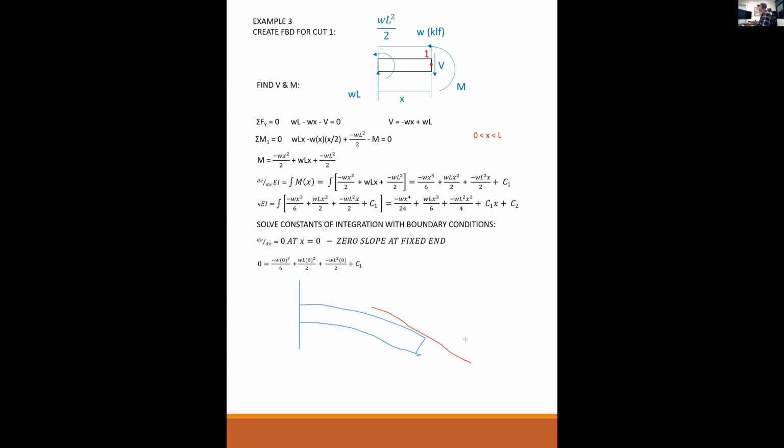And that's a negative slope. It's a negative departure from the horizontal. And if I took a point over here, that's the slope at that point, say right there, it's less of a slope. So the farther out on the cantilever, the more slope you have. But the important thing to know is that at the fixed support, the slope is exactly 0. So this angle with horizontal, that angle in radians, is dv dx. That is the slope. Does that help? Yeah, it's very obvious. Thank you. Okay.